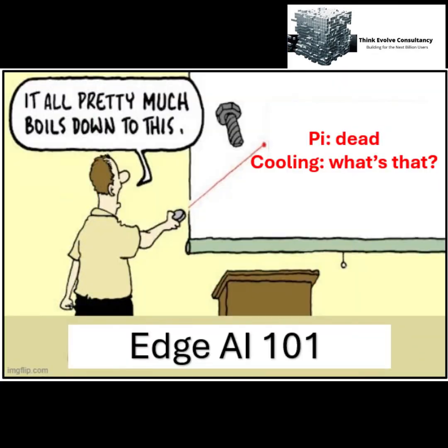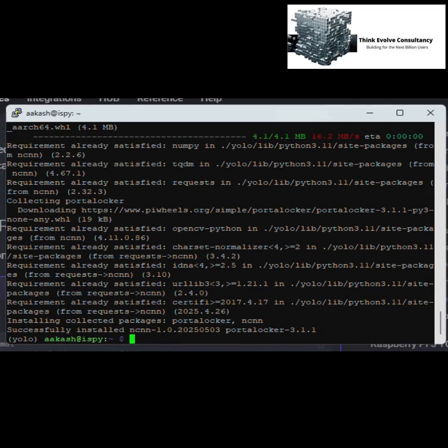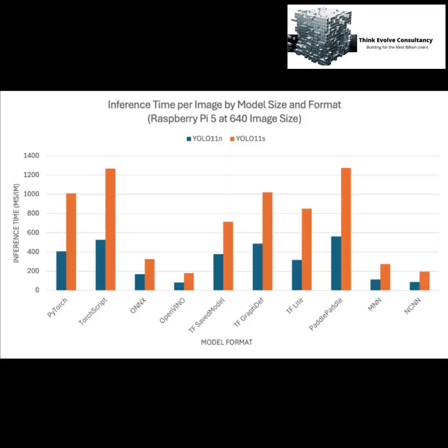So now that we have got the reliability part out of our way, let's check how to download and make our first inference. YOLO models can be exported to NCNN format. This format is highly optimized for mobile devices, consuming minimal resources while delivering quick and precise inference. It is lightweight and has a very high speed of inference on an edge device like a Raspberry.